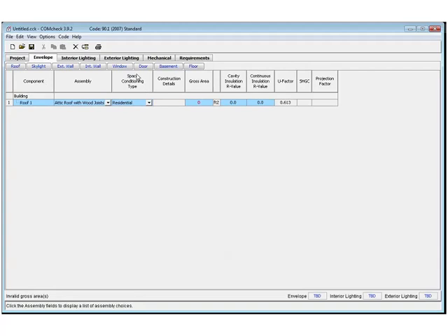If you come over and let's take a look at these columns, I have a space conditioning type that I had two that I chose from in the project tab that I needed to find and make sure I'm choosing the right one. Construction details, this really is applicable to alterations, so it's grayed out. You have gross area, got to look at what type. Slab is the only one where you enter linear feet. You have a cavity and continuous column that you could be working in one or both. The U factor, this isn't something you would enter for this assembly. Then you have the solar heat gain projection factor, and of course this would not be something you'd enter for this one as well because it's a roof and it's grayed out.